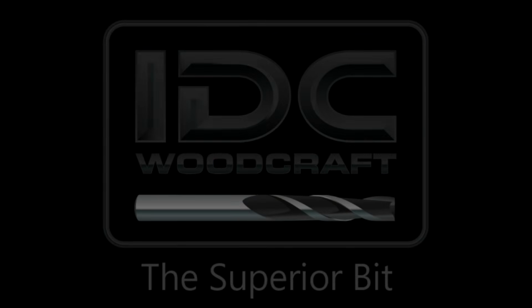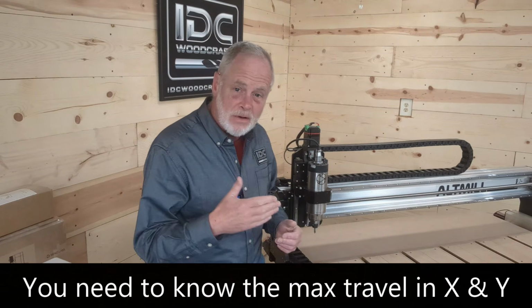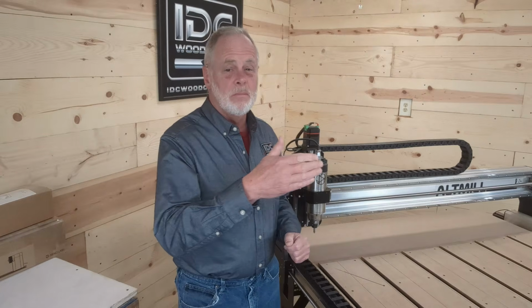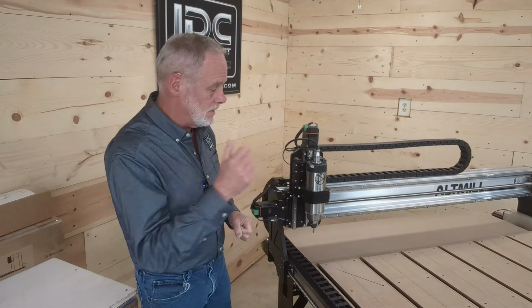Before you design your grid, there are two things you need to take into account with your Altmill CNC router. The first one is the max travel distance in the X and the max travel distance in the Y. The Altmill 4x4 has a max travel distance of just a little over 49 inches by just a little over 49 inches. The Altmill 2x4 has a max travel of just over 49 inches by just over 25 inches. And so when we build your grid, it's going to be based on that size of a project. So you can take advantage of the entire grid space or the entire spoilboard space.